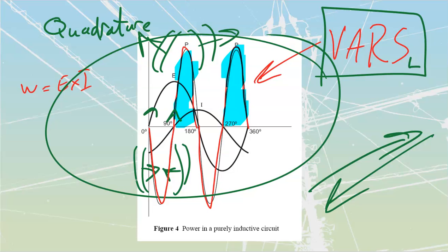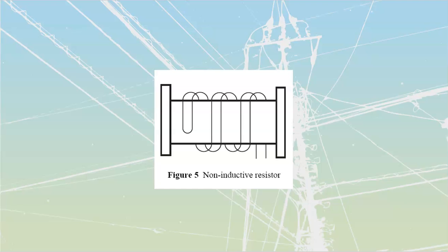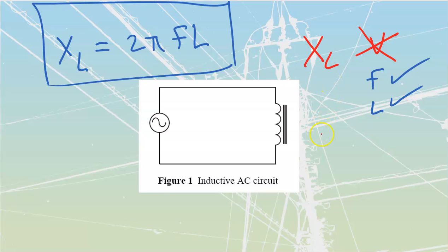Okay, the last little bits that we have over here for inductors in AC just deal with inductors that are specialized, actual inductors. There's a short brief where they start talking about the Q. The Q of a coil is just going to be the quality factor of a coil. It's going to be a ratio of its inductive reactance to its resistance.